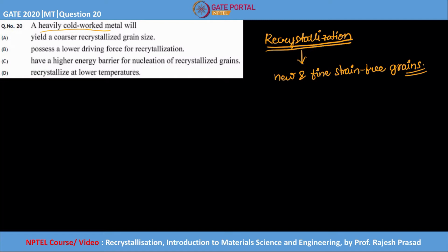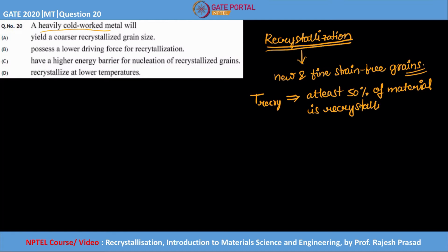But what about the temperature of recrystallization? At what temperature will the recrystallization take place? Let us call it the recrystallization temperature. We have a standard definition: the temperature at which at least 50% of the material is recrystallized in 1 hour.